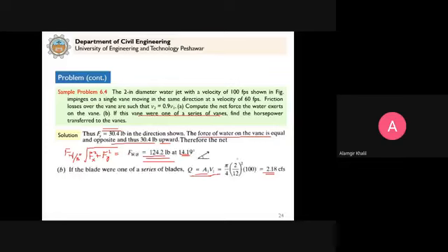It means the discharge hitting a single moving vane is less, 0.87. And here this is 2.18. So for a series of moving vanes, the discharge hitting the vane will be more. Because if it misses the first vane, the remaining will hit the second vane. So it means the full discharge is utilized for a series of blades. So then in that case, Fx you can calculate now with q, not q dash.